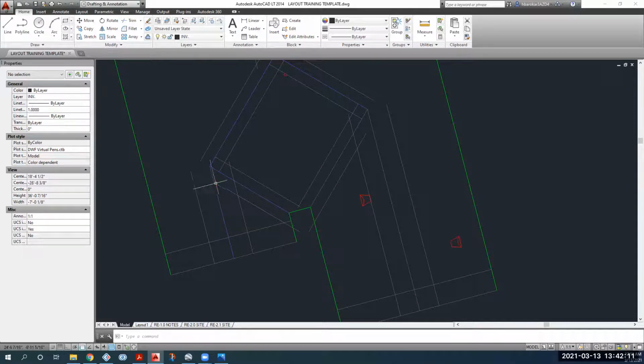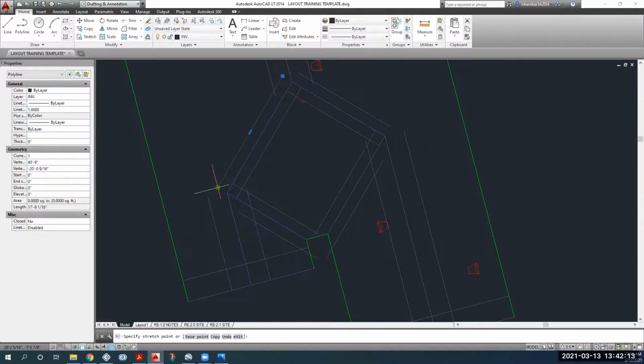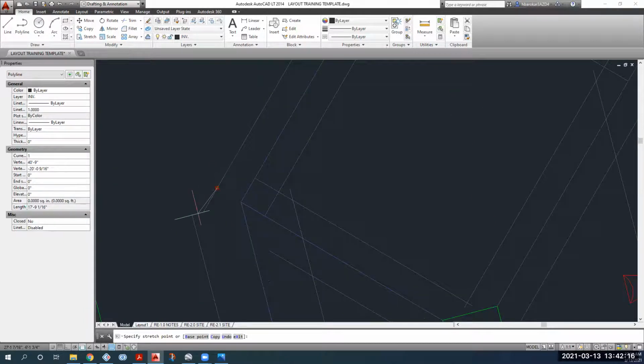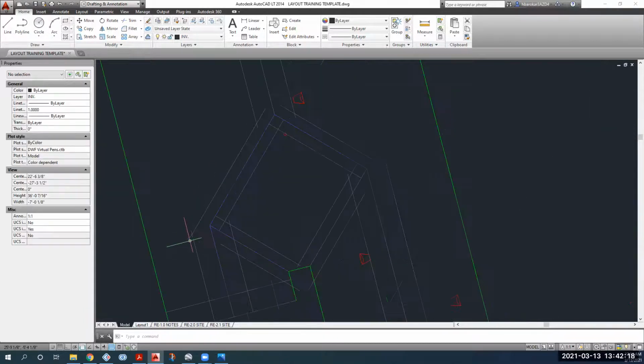Yeah. Okay. So as a general rule of thumb, only for the ridges we are using the projected scale, and for the gables and hips and valleys, we are not. We are just doing it unprojected, right? Right. So we'll just take that as a rule of thumb.